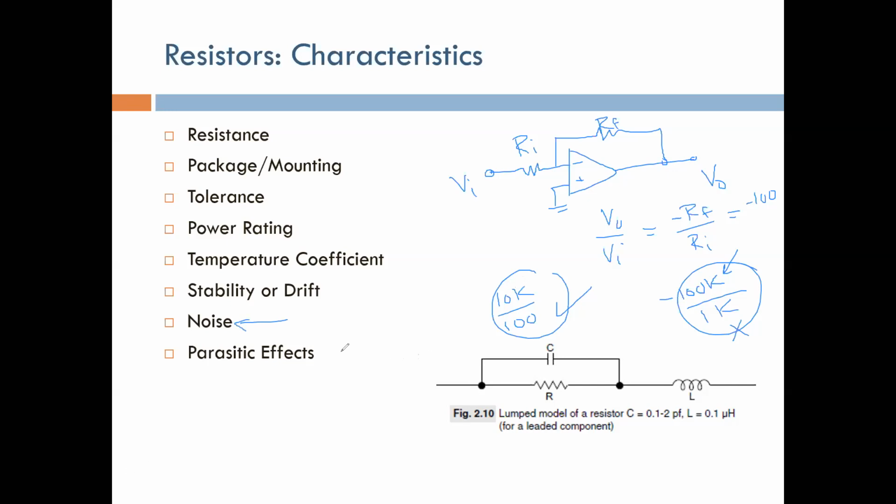The last thing we need to talk about, but not in much detail, but you need to know about, is the parasitic effects of your resistance. Basically, what we assume is that when we buy a resistance, we buy something that looks like this. What we actually buy is something that looks like this. It has a stray capacitance between its terminals. As we're going to talk about in the capacitance part, the resistance practically looks like this, right?